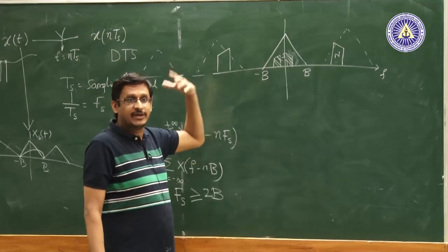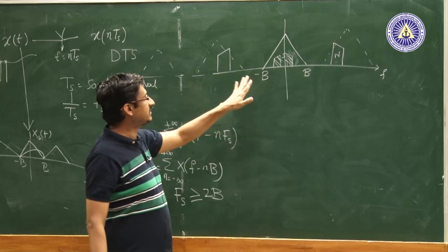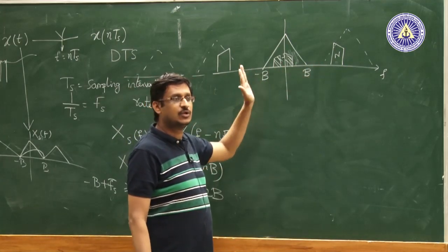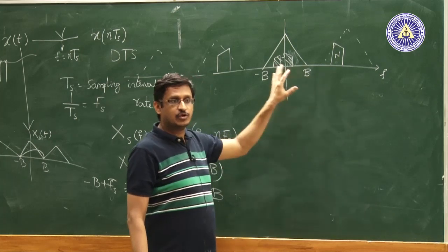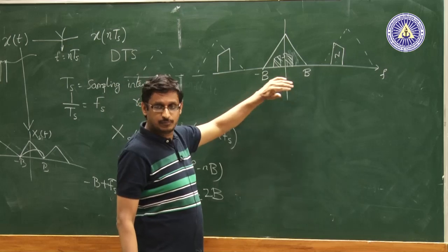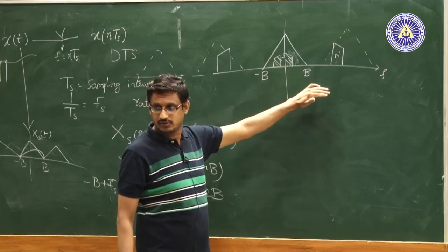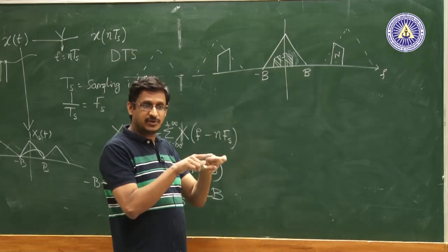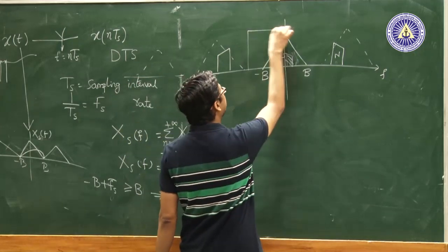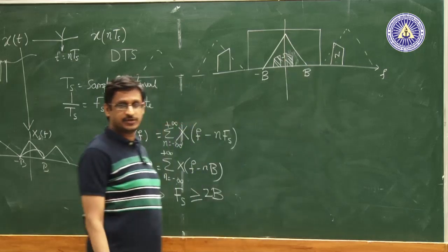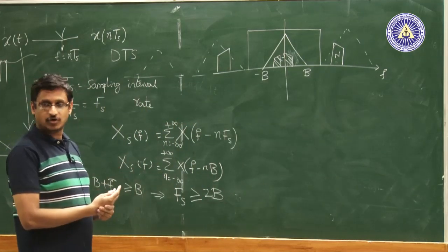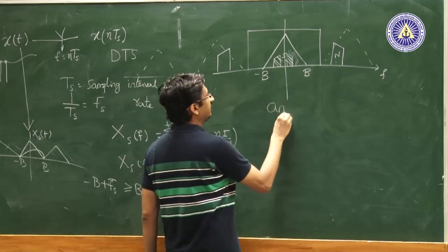In the original case, you could have with some approaches, because signal and noise were separate, but after converting the original signal into a discrete time signal, your noise is now within the band of interest, and this is one of the major problems with discrete time processing, that noise can actually seep into the bandwidth of interest. In order to avoid that, you have to limit the bandwidth of the signal which you are sampling to whatever range you want, by what are called anti-aliasing filters.